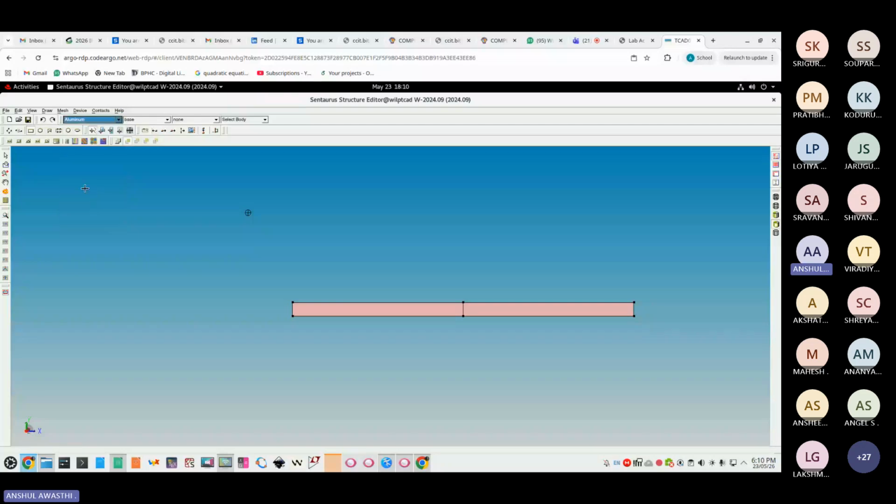Aluminum. And these things you have to see now. Contacts are on the end side. So if you see here, this point is 0.5 micrometer or 500 nanometers. And I want my aluminum contacts to be 10 nanometers after where my P region is ending and 10 nanometers before my N region is starting.